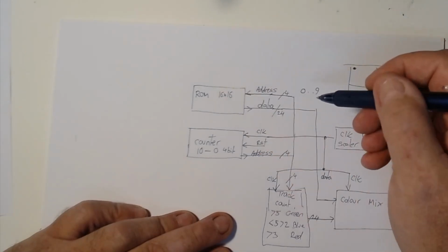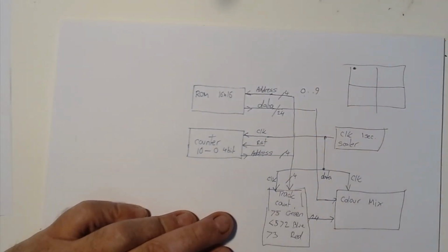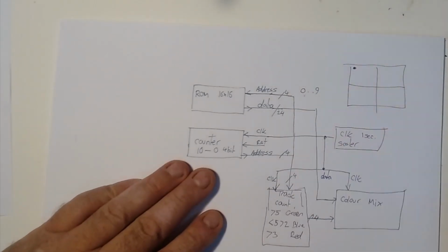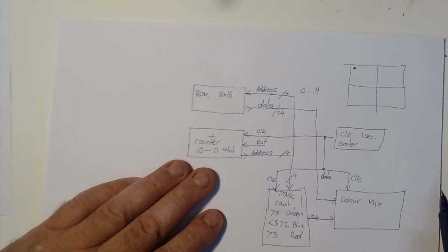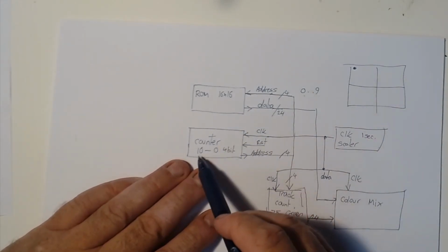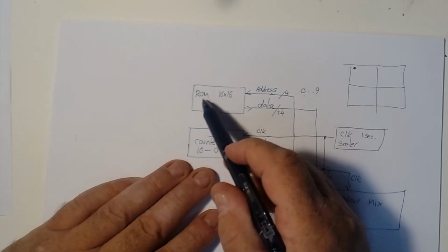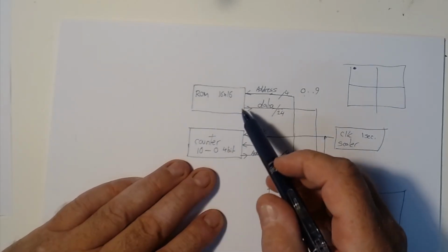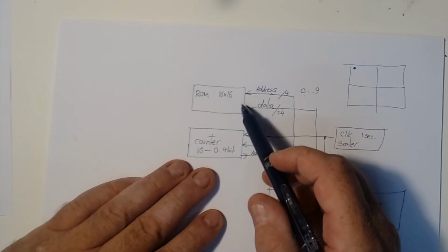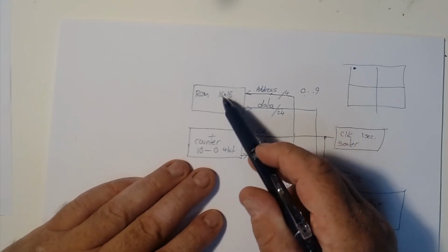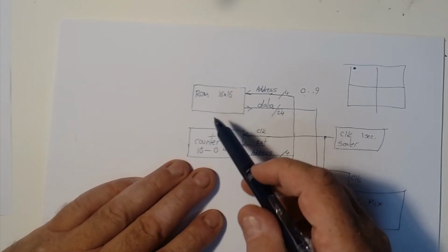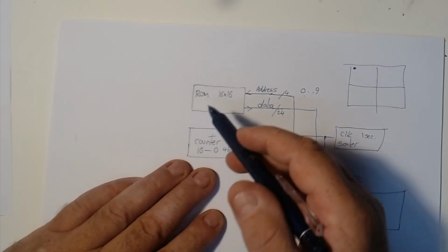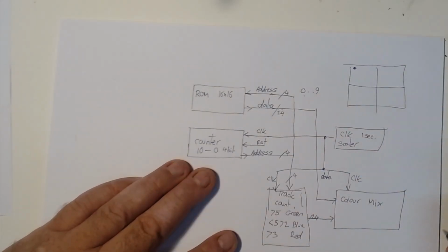So the way this has to output, we're actually going to need to change that addressing a bit. This is the beauty of going through and thinking it all out at this level, is I'm starting to see the holes in my system. So my simple counter 0 to 10 would be fine if I'm outputting the entire digit, but I don't want to, so I need to break that up, that I'm actually, for each of my digits, outputting whatever 16 by 16 multiplies out to. I need to do them one memory location at a time and put that through.